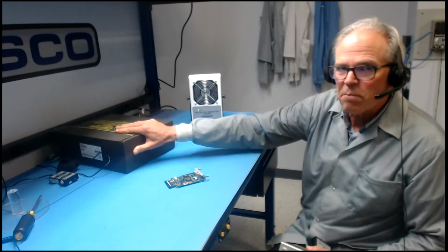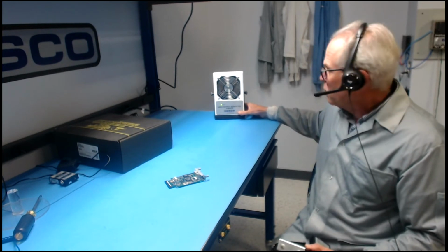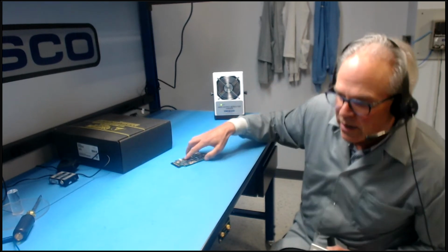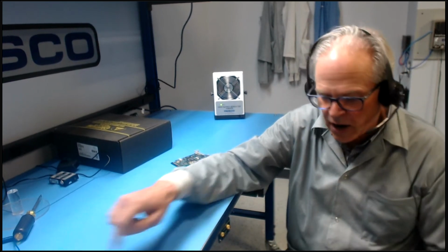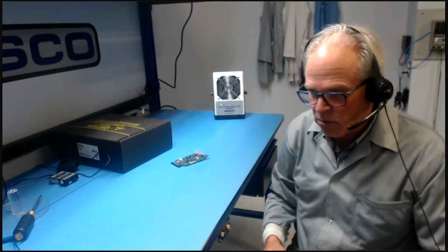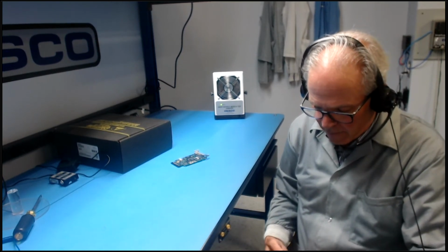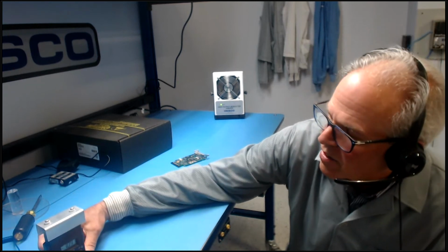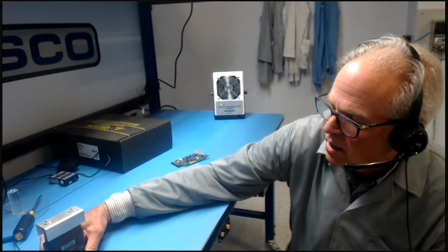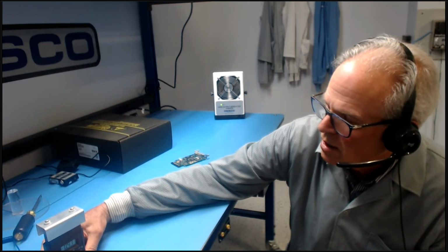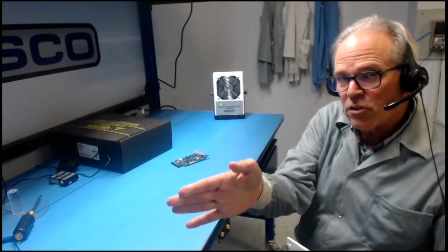The other thing is that sometimes companies use benchtop ionizers to cover the whole bench, which is fine. But if you're thinking that it's going to work, can you see where I'm pointing? Down at the far end, you need to find that out, because if you're working on devices down there, so I got it there. It's going very slow, 800, 700, 600, 500, 400, 300. So you can see the distance matters.